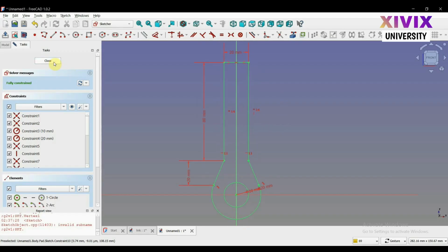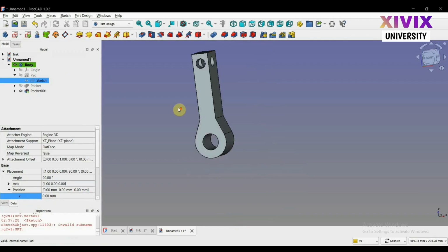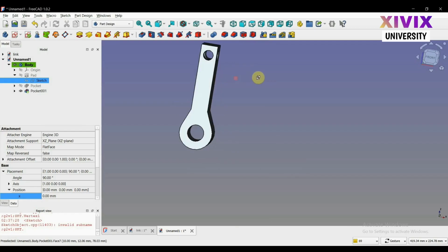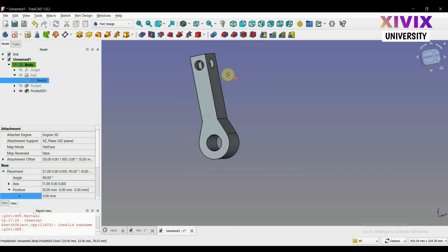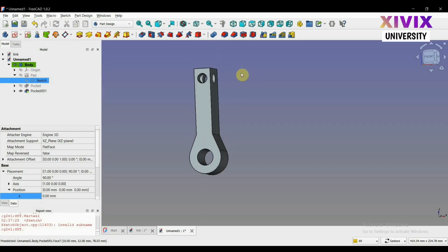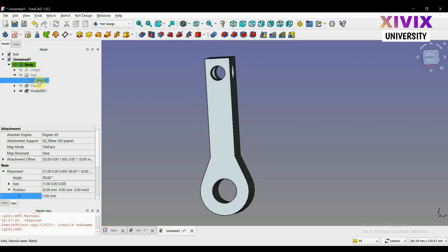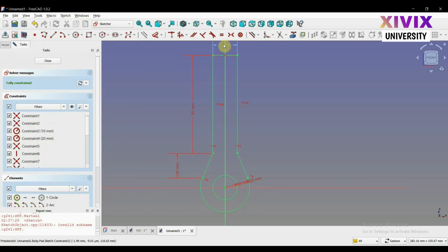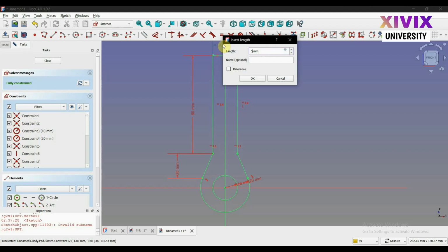design is the original look of this yoke link. And now you can see it's no longer the original design for the yoke link. In other words, the solid has been compromised. I'm going to change the horizontal length into, let's do 55 millimeters.